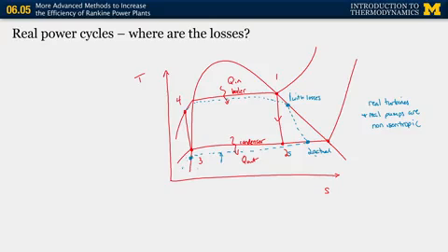And in the case of the pump, non-ideal performance is actually going to move it like this. So this is the actual exit condition. Again, I'm going to aim for the boiler's ideal pressure, and this is the isentropic exit condition. So again, the losses are for each component, and the way we describe those component losses depends on the type of function that we have.